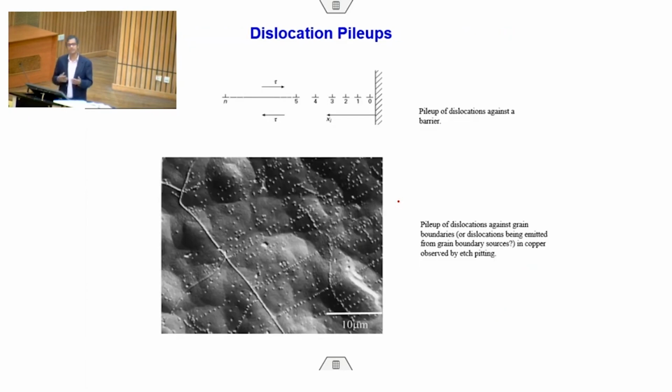So, because of these two aspects, one is that the grain boundary structure is different, and the other is that the grains are not oriented the same way, dislocations moving in one grain will not be able to directly move into the other grain. That means dislocations will find the grain boundary as an obstacle to move. Well, you can also imagine the dislocation can jump over and reach the other grain.